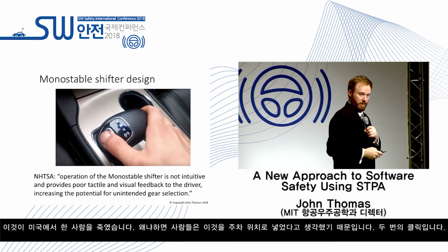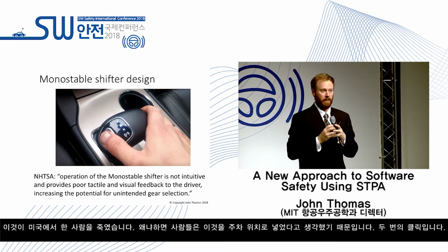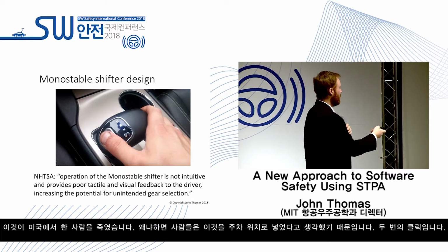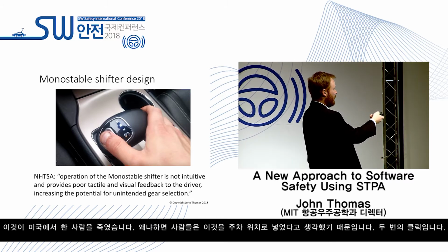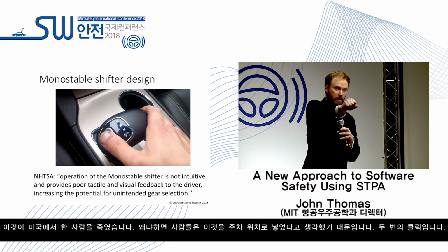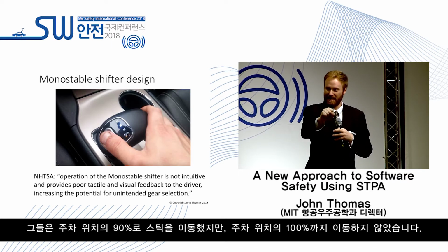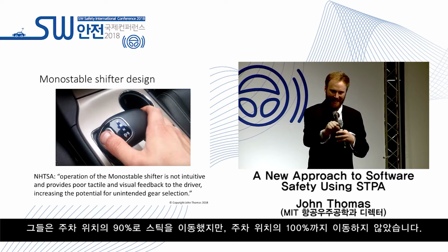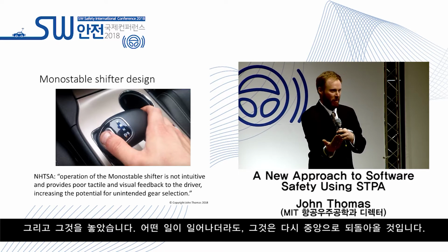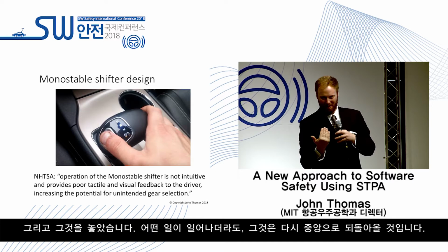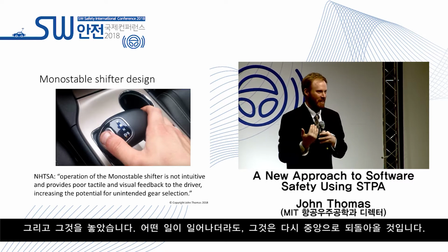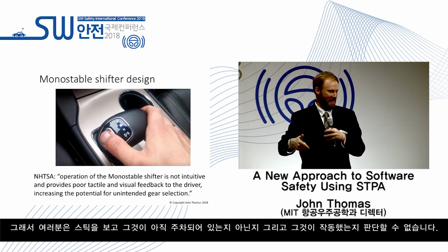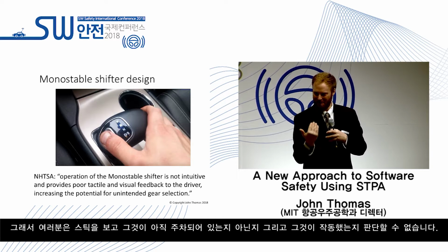This killed a person in the US because the human thought they put it in park, 2 clicks. They went 90% of the way to park, but not 100% of the way to park. Let go. No matter what happens, it will bounce back to center. So you cannot look at the stick to determine if it's still in park or not, if it worked.